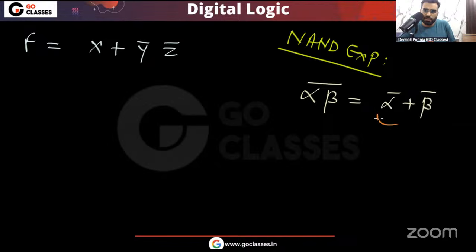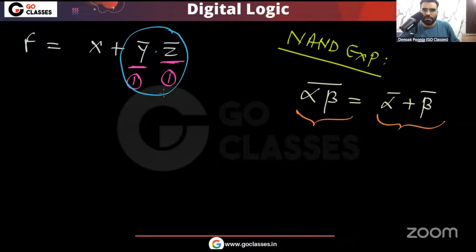So remember, this is a NAND expression, this is not. Now let's assume someone is thinking like this, that okay, sir, for z complement I need one NAND gate, for y complement I need one NAND gate, then for this AND operation we need two NAND gates, because we already know for alpha and beta we need two NAND gates.